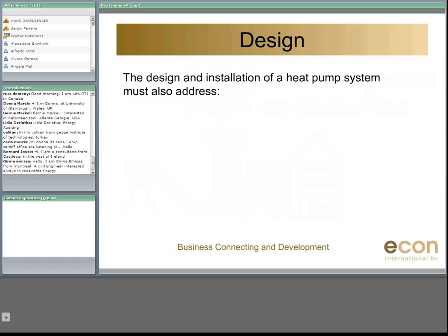To make sure that your heat pump has the correct size, please ask a heat pump contractor to help you with that, because it's not very easy to select the right size of your heat pump. So always ask an expert, can you help me with that? Because if you have too high a capacity for your heat pump, your cycle will turn on and off more, resulting in higher energy use, and perhaps also a shorter operational lifespan of your heat pump. And since it's a very expensive device, I don't think you want a shorter lifespan.